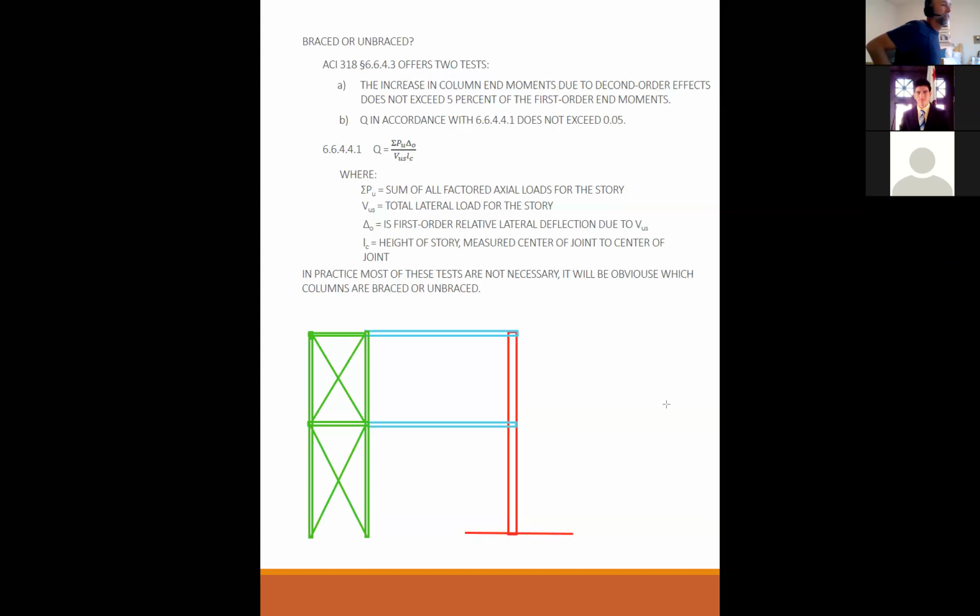I'm not sure if everybody's high school had grandstands for the football stadium or the track stadium, but a lot of those steel structures that are the stands that you watch around the field have these guy wires or 3/4 inch thick steel rods that X brace the system. So that's what I'm thinking about here, fairly light gauge steel with X bracing.